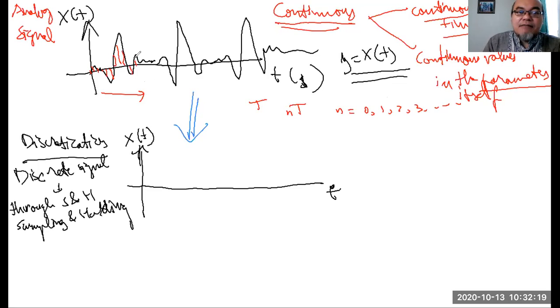With the periodic sampling period, something like that. So what is being captured is the value of that signal at that particular sampling period. The red line is just to show where the sampling happens at the particular time. If we redraw it as a discretized signal, it will look maybe something like this. It's not perfect, just to show you how discretization happens.